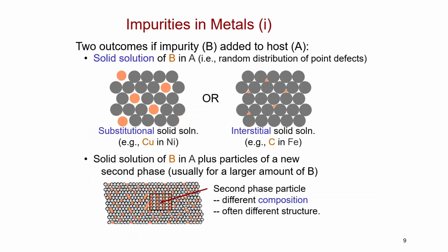Now we are going to discuss impurities. When we have some impurity in a metal, what will happen? Impurities are not a disadvantage all the time. We purposely add impurities to metals to improve properties. For example, we add carbon to iron to make it steel. When we have carbon, it's stronger, so even though we call it an impurity, it's an advantage for us.